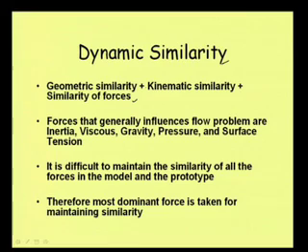But to have dynamic similarity, we have two prerequisites. In fact, we can summarize that to be one prerequisite, that kinematic similarity needs to be maintained, because for kinematic similarity the geometric similarity already needs to be maintained. Or explicitly, we can say that for having dynamic similarity, geometric similarity as well as kinematic similarity need to be maintained, and then we will have to have similarity of forces, and combining all these we get dynamic similarity.